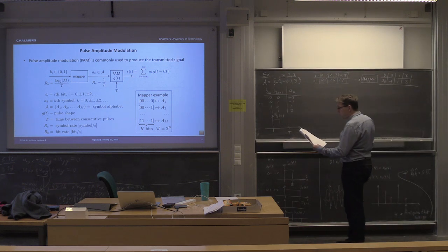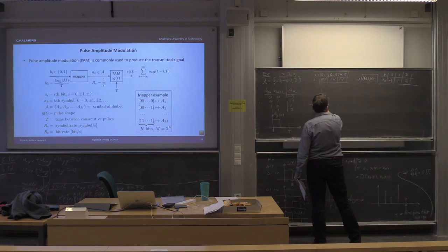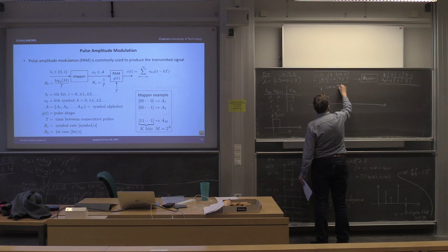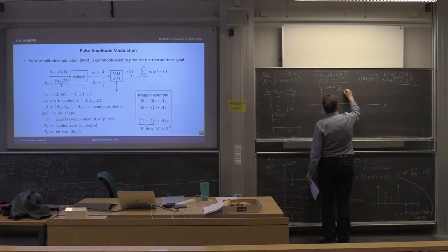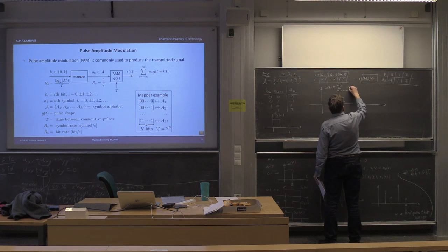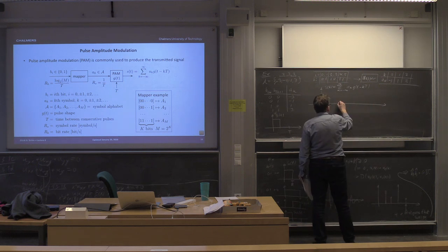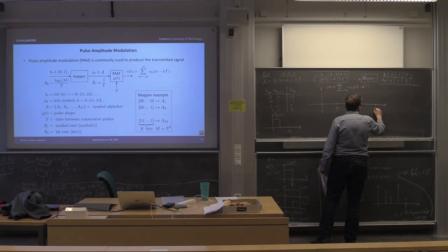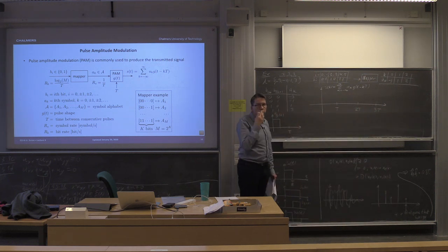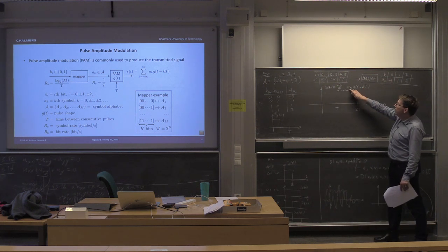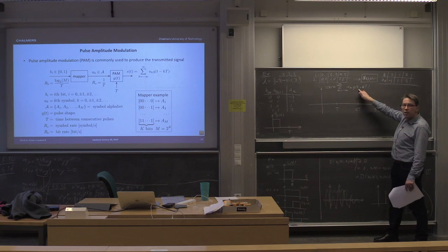And now let's convert this into the signal. So it's a sum from -infinity to infinity, Ak g of t minus kT. Okay. So here, every T seconds, we start a new pulse. We transmit a new pulse. Okay. So for k equals 0, put in k equals 0 here, we see we have A0 times g of t.